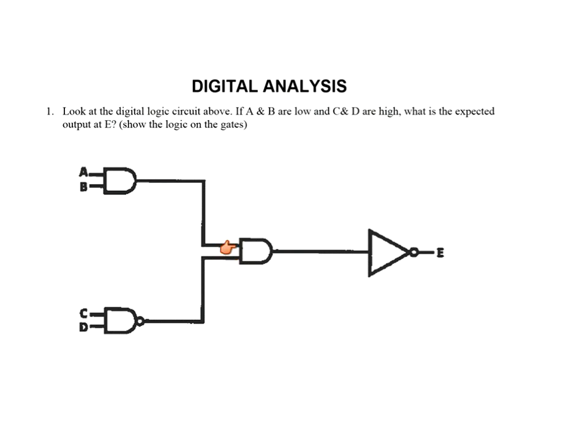If I have a 0 on either one of these, I don't even have to evaluate this down here. The reason is, this gate up here, I know I'm putting 2 zeros in, 2 lows. I'm going to get a low out, and any low into an AND gate makes the output low. So my output, after it goes through the inverter, would be a high. The output for this would be a 1. And I didn't even have to do the full evaluation, just use my knowledge about what was going on right here.